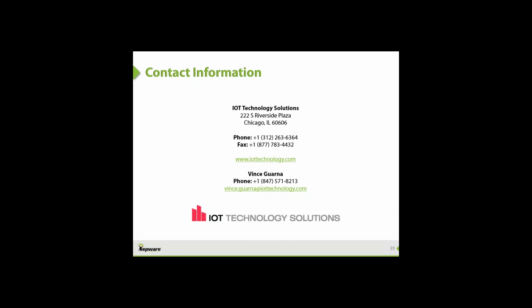Okay, great. Thank you for that. And then a question for the Kepware side. Kepware integration through OPC UA, so as opposed to what we showed with our RESTful interface. Boulon's asking, what about integration there? So you want to answer that, Ray? Yeah, so for the demo we used our IoT gateway, which leveraged HTTP to publish data up to the ELIoT platform. Now, KEPServer does support OPC UA. For this demonstration and for architectures and solutions moving forward, really, you could choose either way. The HTTP or MQTT agents do support encrypted and authenticated connections.